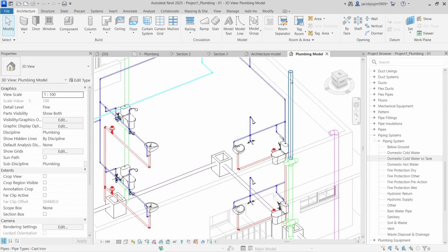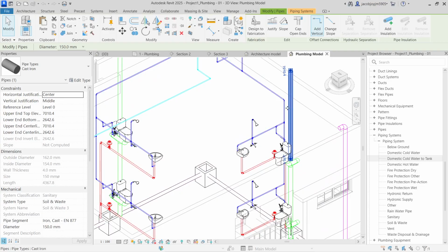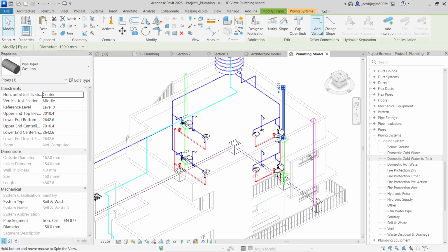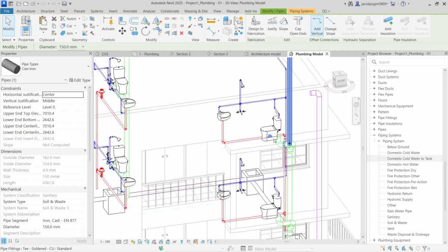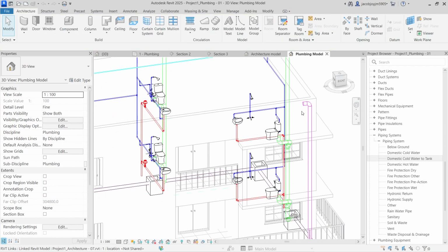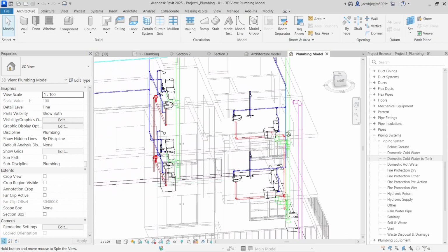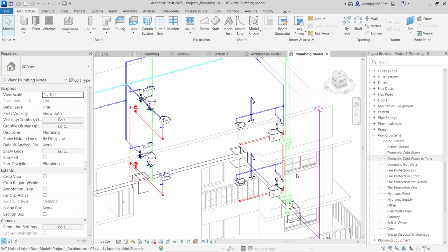So we need a vent pipe also for all the water pipe and soil pipe. We need a vent pipe. Okay, actually the P trap we have to provide, but the latest WC will not require a P trap. Okay, but it's again up to your engineer how they want to provide.